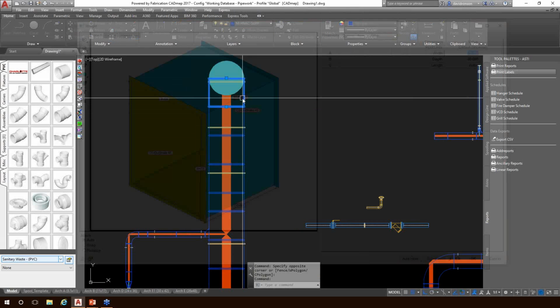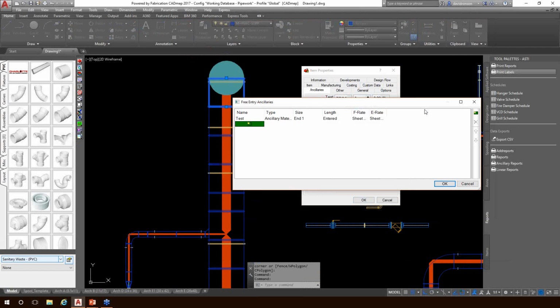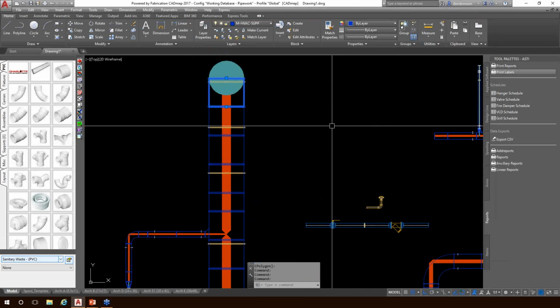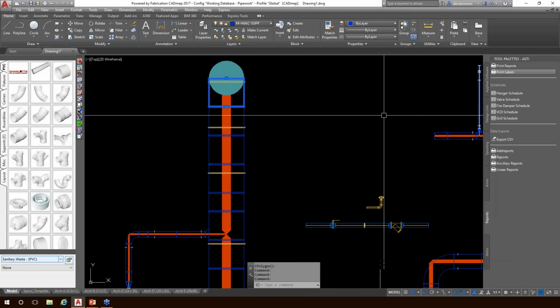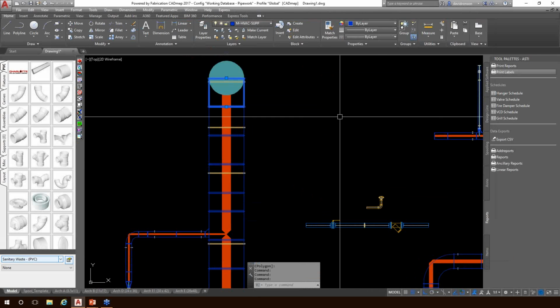But they can be applied at the fitting themselves. In some instances, you're going to want to apply them at the fitting. Ideally, especially if you're doing this in retrospect, you're going to want to put it in at the connector. Because if you do it at the connector, the information is going to take hold on your existing model. If you apply it at the fitting level, you're not going to be able to take advantage of that data until that fitting has been placed into the model.